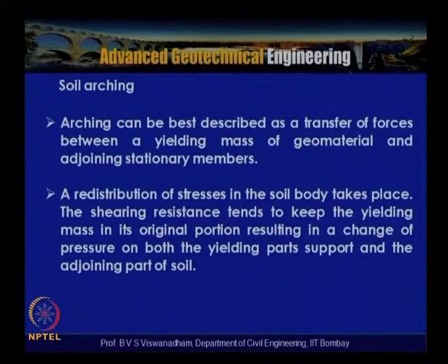So a redistribution of stresses in the soil body takes place because of the participation of arching. The shear resistance tends to keep the yielding mass in its original position, resulting in a change of pressure on both the yielding part's support and the adjoining part of the soil.